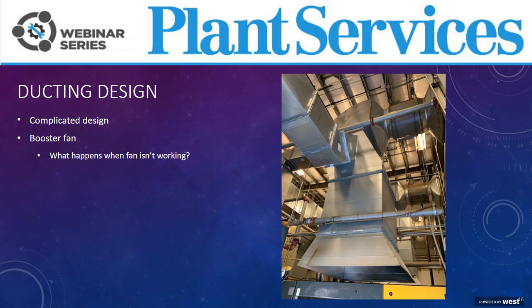When multiple ducts come together, how can you ensure that that hot air is going to be removed? Well, a booster fan, which you can kind of see there at the top right, is going to help remove the necessary heat, but it's got to be sized appropriately, and you need to always consider what happens to the equipment should the booster fan fail.